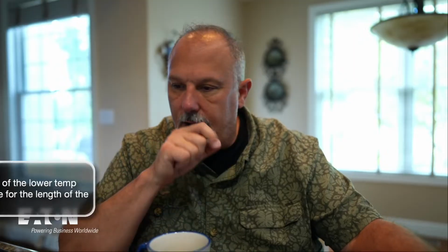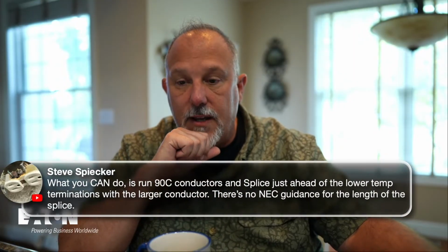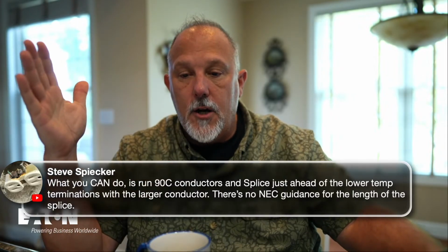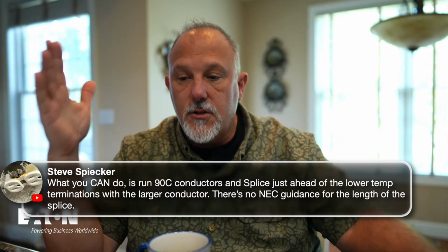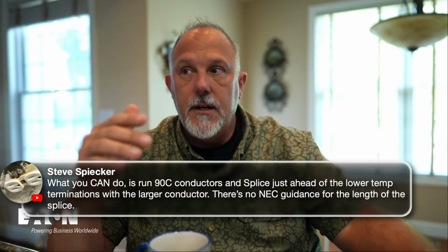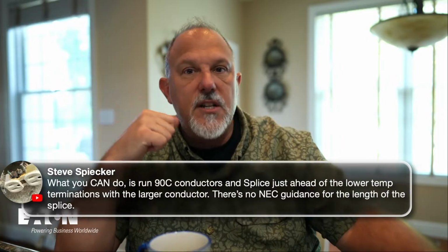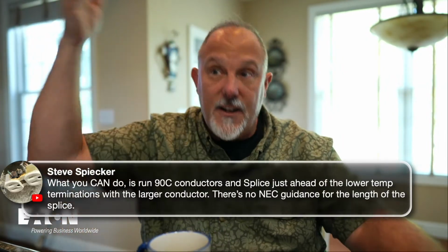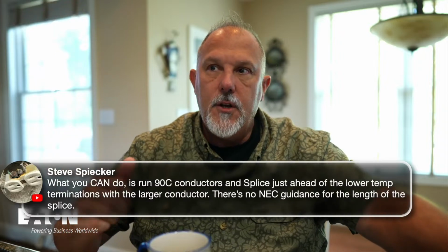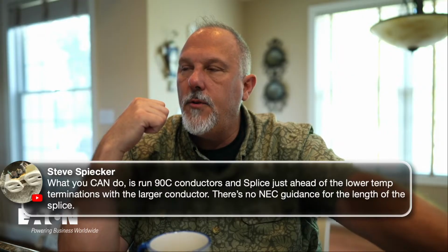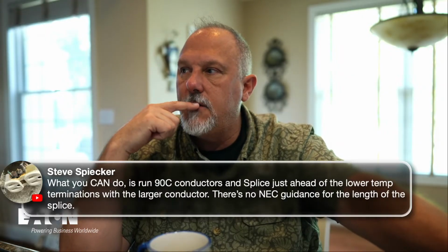And then I'm going to get back to you, Laurel. Hang in there. Steve says what you can do is run 90 degree C conductors and splice. Yeah, there you go. Lower temperatures, larger conductors. There's no NEC guidance for the length of the splice. You're absolutely right. I don't disagree with you, Steve, that's what I was just saying in different terms. But that splice, I'm not sure where you would want to do that.